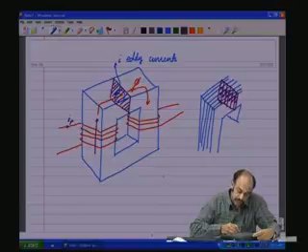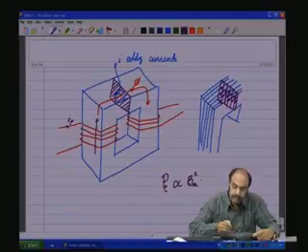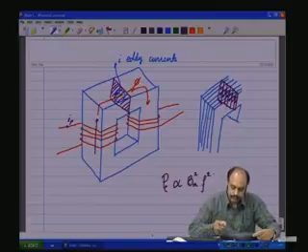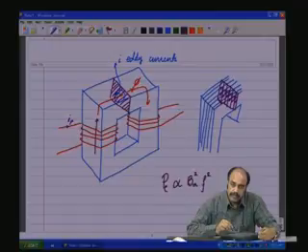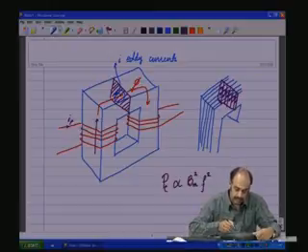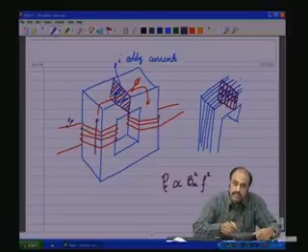There is an empirical relationship for the eddy current power loss, which is proportional to the maximum flux density square and frequency square. So, the higher the frequency, the higher the eddy current losses, and the higher the maximum flux density of the core, the higher the eddy current losses, because the current that is induced is directly proportional to the flux density.